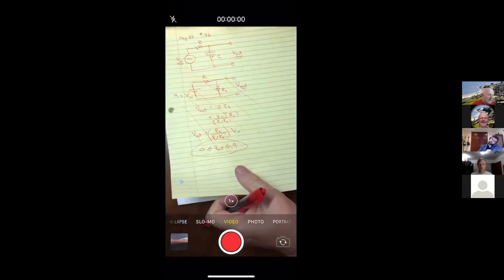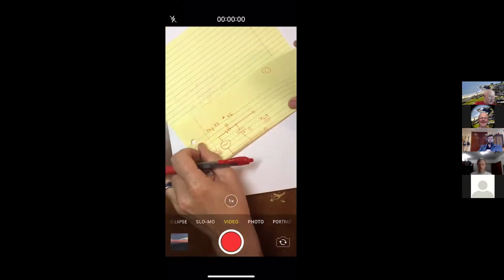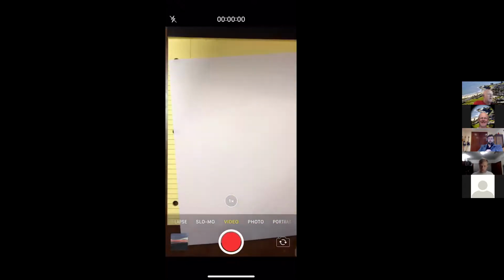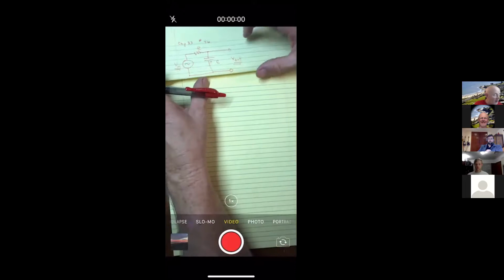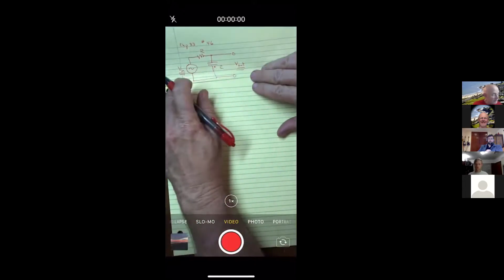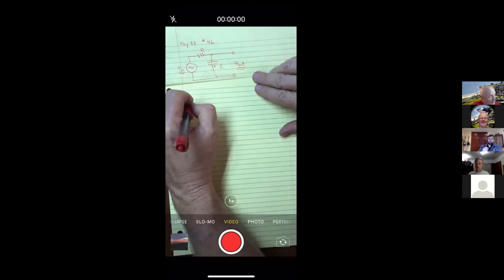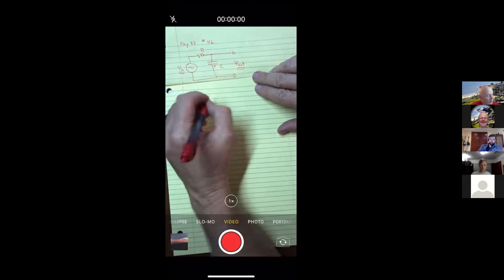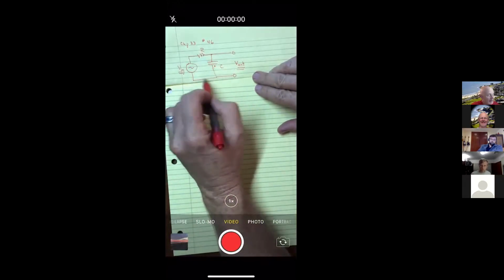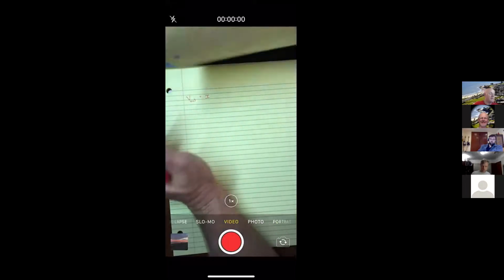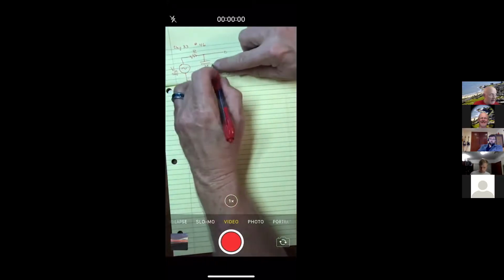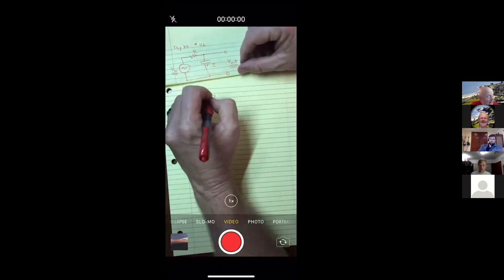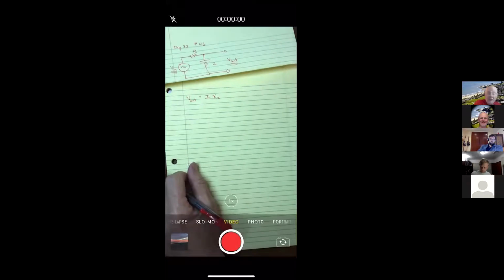Okay, so why don't I take this first page and just tuck this away so I can see the circuit, but also I could flip it over and talk about this circuit divider, because watch this. Here's what I would say. I would say, just like I did before, that the voltage out is equal to the current that I get in this circuit times the resistance R2. Now this doesn't have a resistance, this has a reactance. So this would be X sub C.